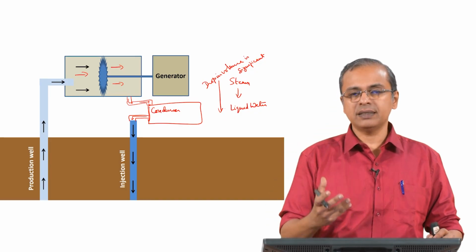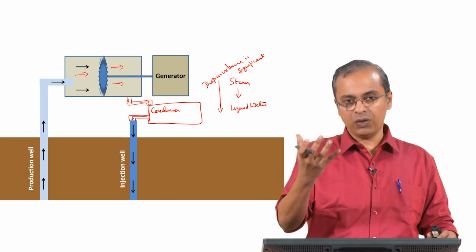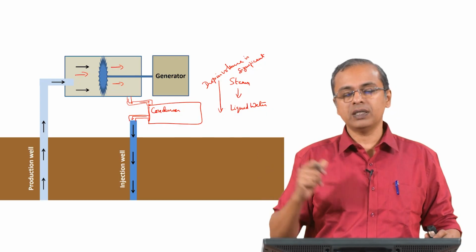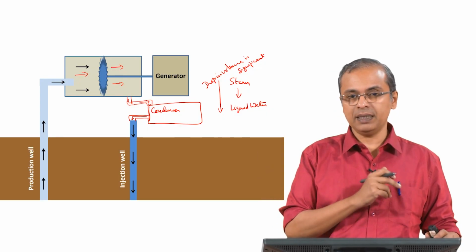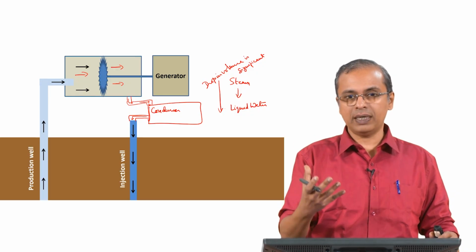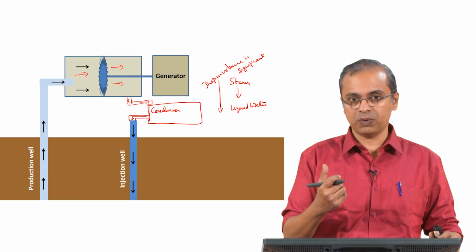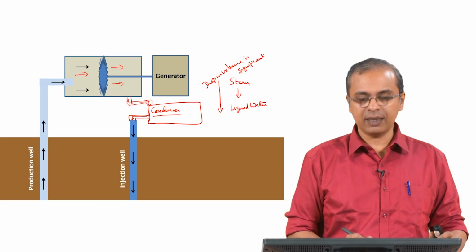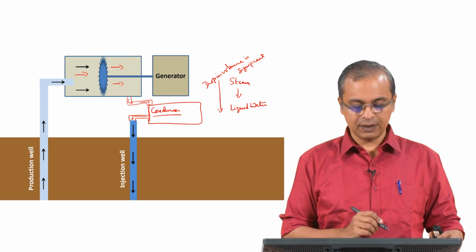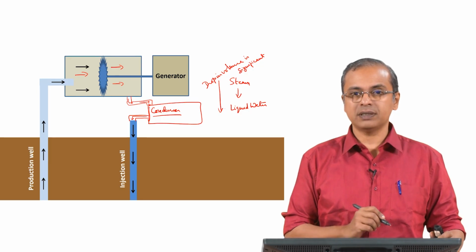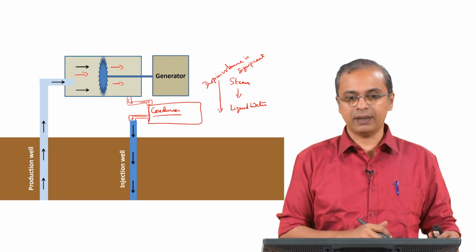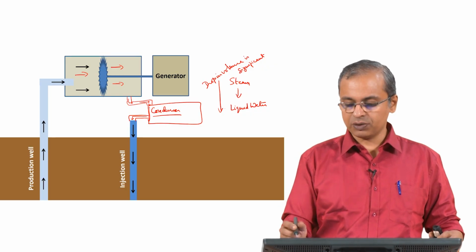So by just the condensation process, by creating vacuum on the exit side, you make the whole turbine system work much better. You are able to extract even more energy out of the turbine, as well as from the superheated steam that arrived at the turbine and through the turbine. So therefore a condenser is a very important part that is added to this geothermal energy process when you have superheated steam, and it significantly helps improve the operation of the plant, and therefore this is always done.